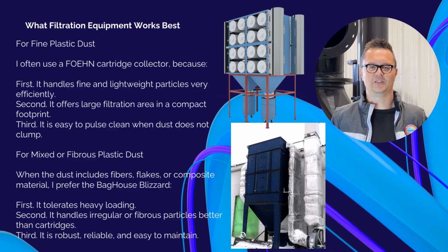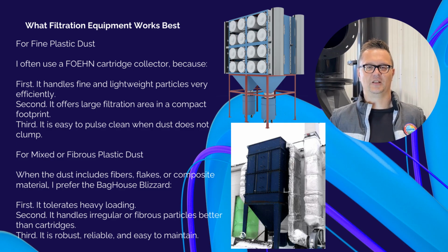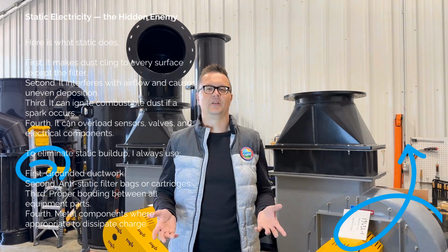For combustible plastic dust, if the plastic type is combustible, I add: first, explosion vent size for the collector. Second, grounding and bonding to eliminate static buildup. Third, an isolation valve for safe duct protection. Fourth, anti-static filter media.